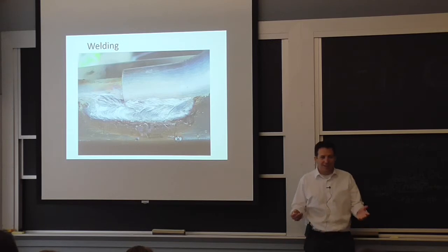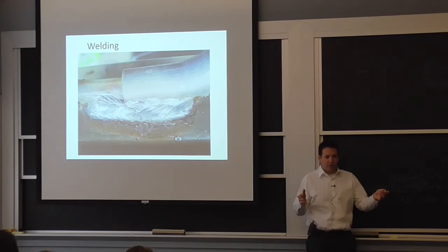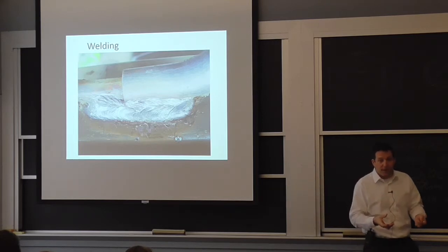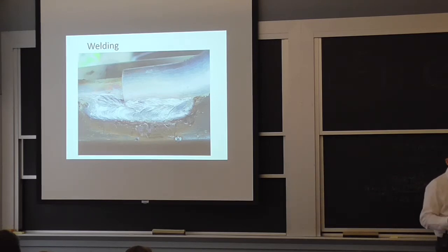One other aspect of manufacturing that is very, very important is joining. It's very nice to think, oh, I'm going to have this pressure vessel, and I want to make it out of this alloy. Chances are you're going to have inlets and outlets to that pressure vessel, and those are going to be the ones you have to worry about in terms of cracks initiating and growing, because it typically comes from multiple pieces coming together.